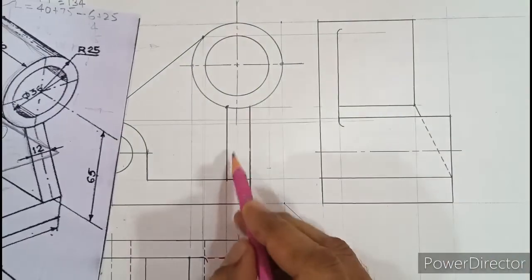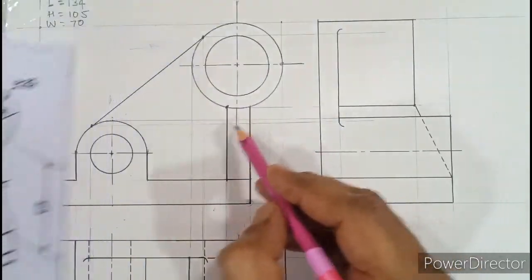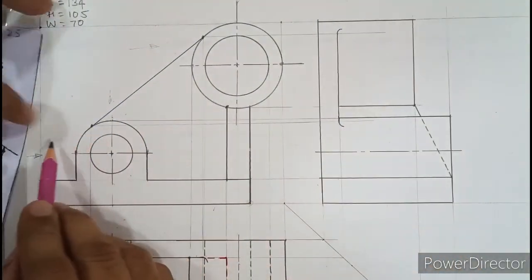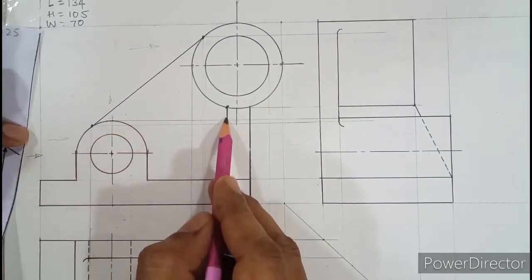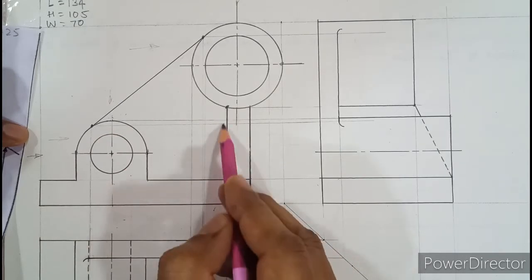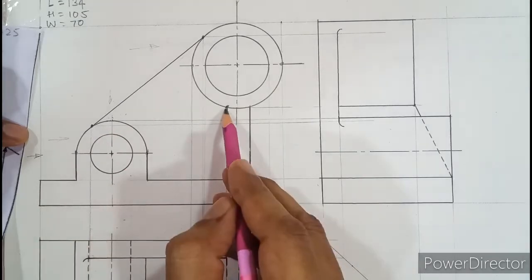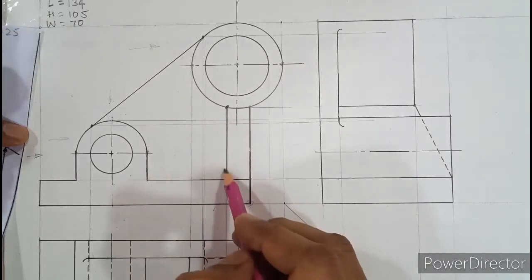And if you try to visualize in this diagram and find out where this edge is, you will come to know that in the side view, when you look from the side, you can see everything above this line. So this much edge will be seen, you cannot see what is below. So this portion of the edge will not be seen. You can see the above part, but the bottom half will not be seen.